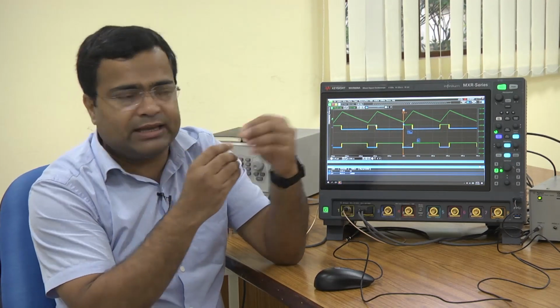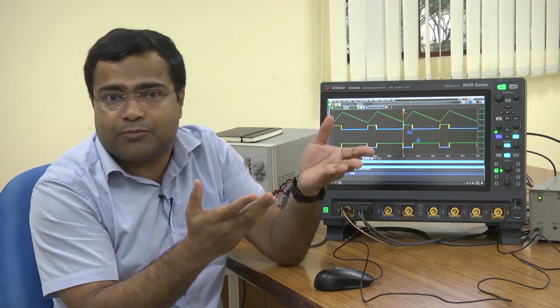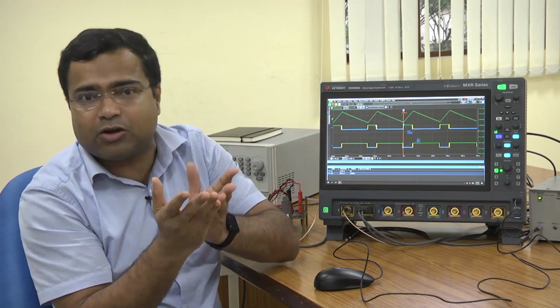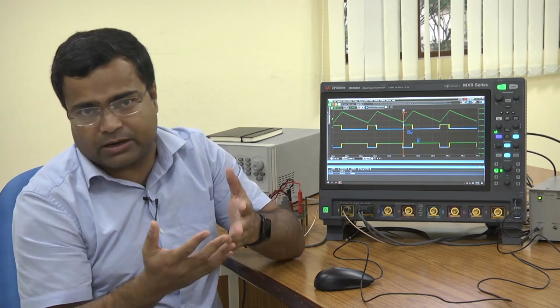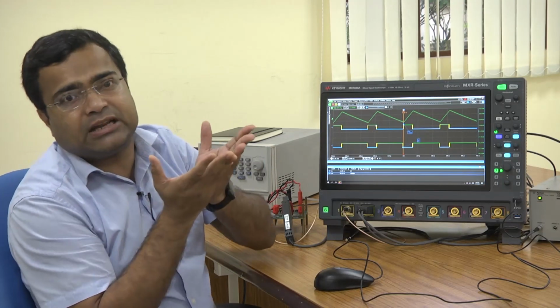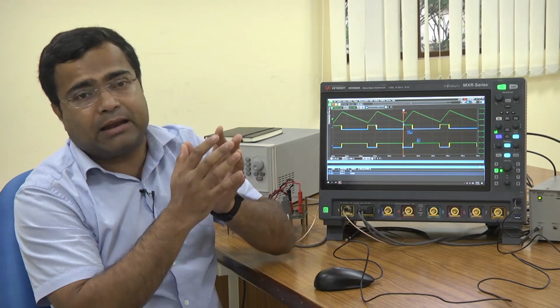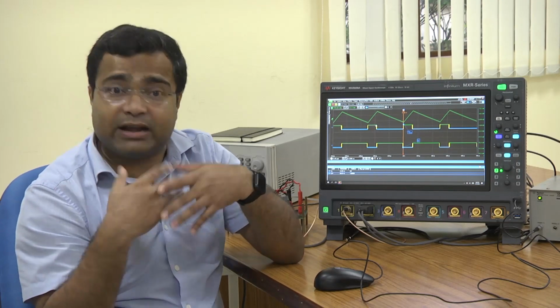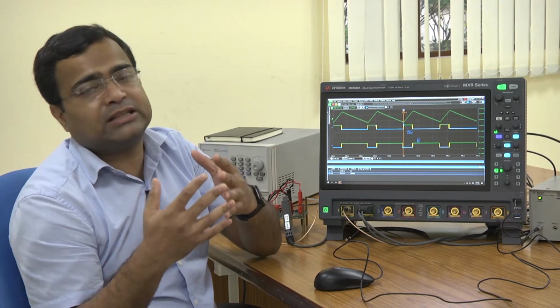Suppose you want to see, here we are using a mixed signal current mode control where the peak current reference is coming from the digital logic, and we are using a D2A converter. But we can also see what is the digital value of the peak current, and that can be analyzed by this digital channel, and you can figure out if any of these bits goes wrong. So you can easily debug the problem in your design and you can rectify it. So that's why I would say the mixed signal oscilloscope is very useful, in fact necessary, to debug, test and validate a digitally controlled converter.